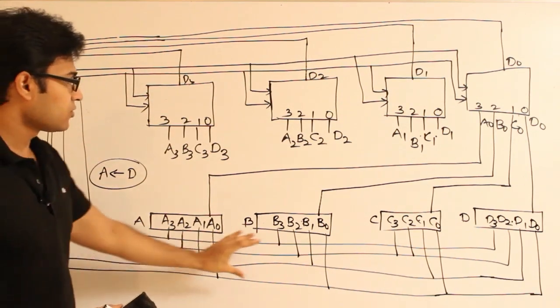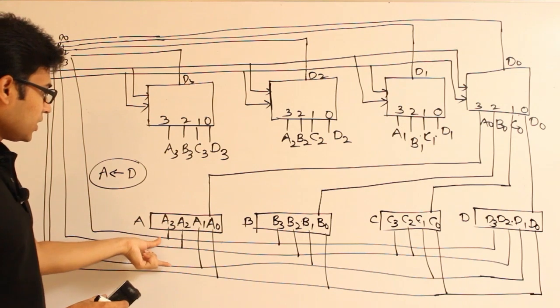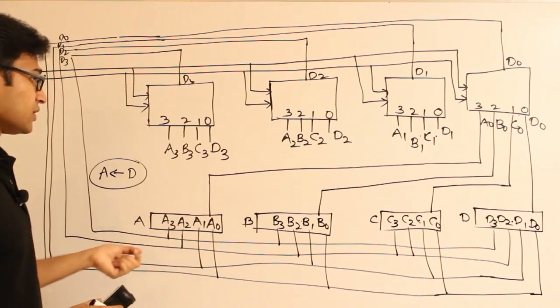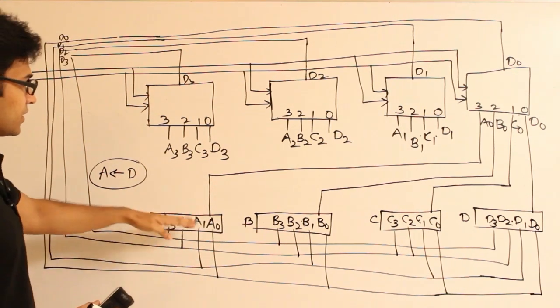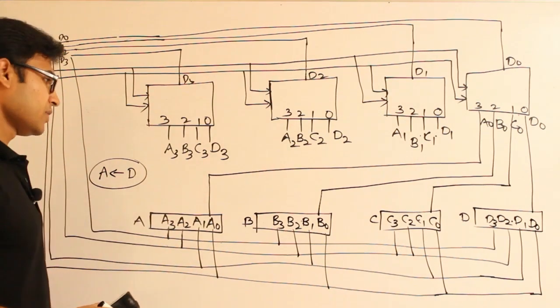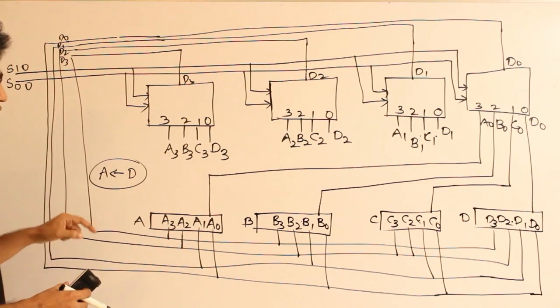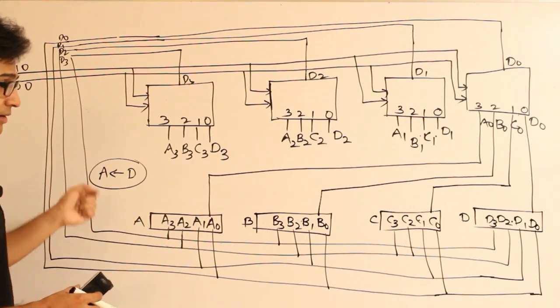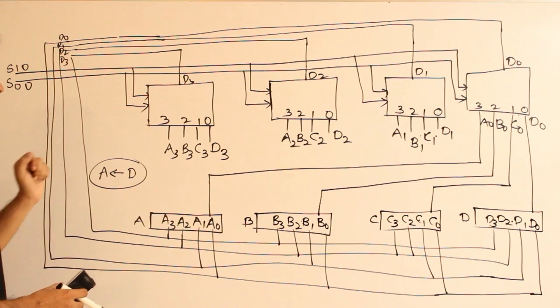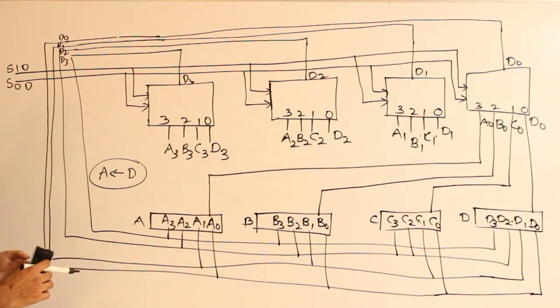Therefore, it is now connected to everything. So all the registers are actually connected to this, but it doesn't mean that all the bits are going to be overwritten with that information. All the registers are not going to be overwritten. Only the register whose load input is activated at that time will receive this information. Got it? So first, what did we do?